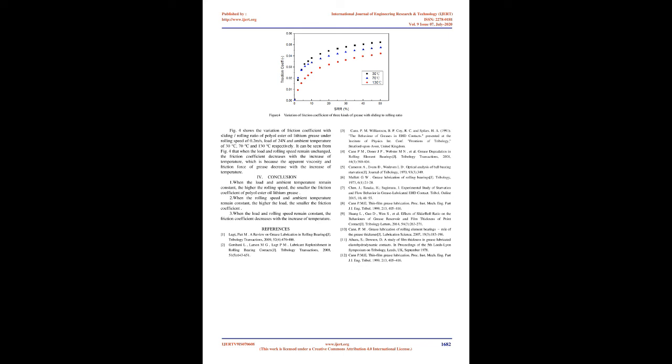For conclusion: 1. When the load and ambient temperature remain constant, the higher the rolling speed, the smaller the friction coefficient of polyol ester oil lithium grease. 2. When the rolling speed and ambient temperature remain constant, the higher the load, the smaller the friction coefficient. 3. When the load and rolling speed remain constant, the friction coefficient decreases with the increase of temperature.